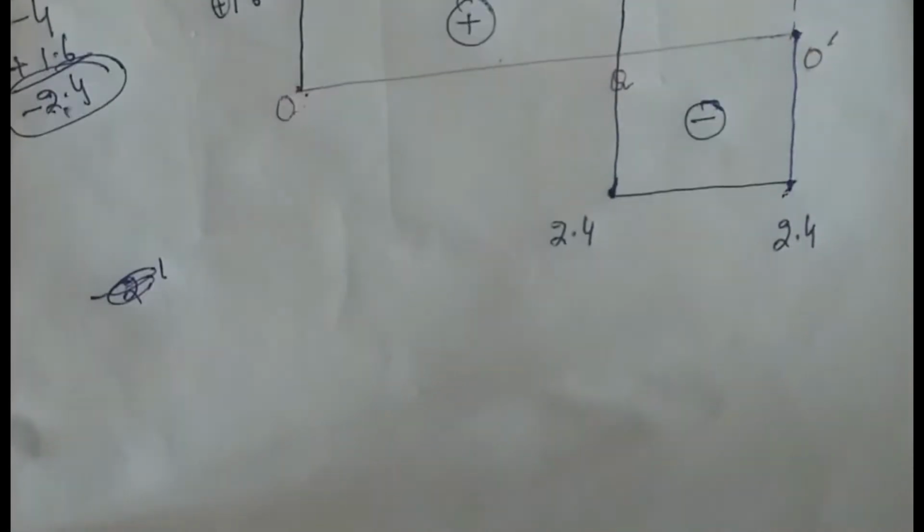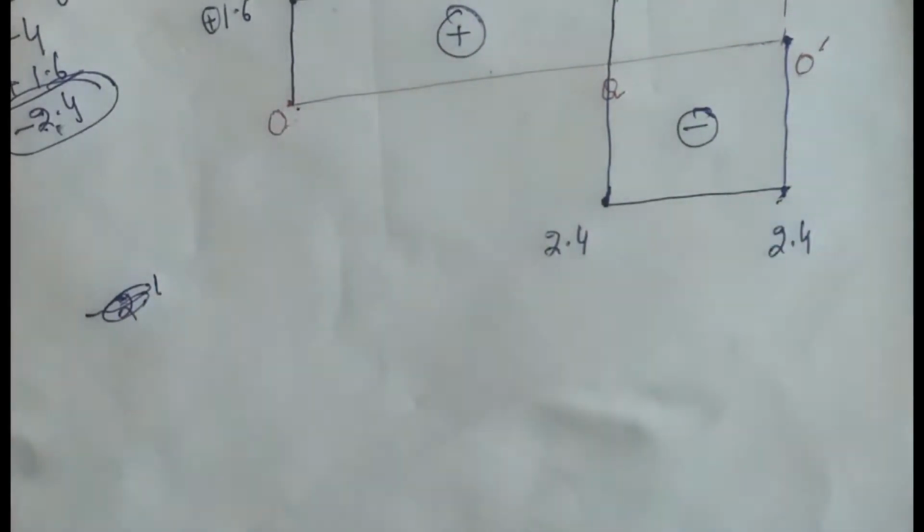Now for the bending moment diagram I will use the shear force diagram, and as we know, the bending moment diagram depends upon the area of the shear force diagram.